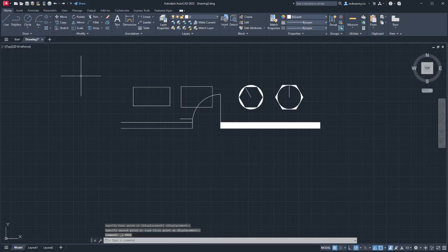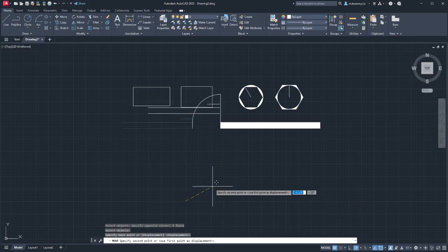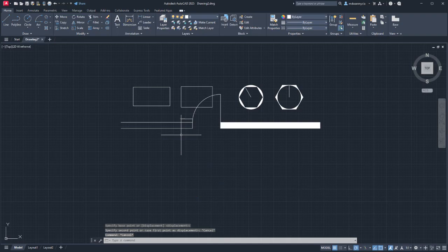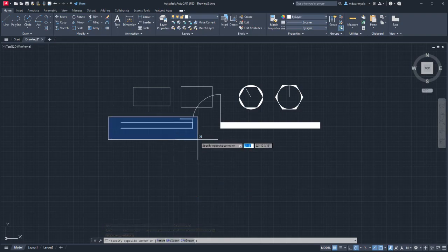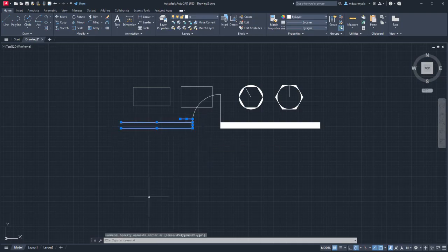Are there any alternative things? If you don't have anything selected, you can select the objects after starting the tool, hit enter or spacebar, and then you can specify whatever your movement might be. So you don't have to select stuff. That being said, for all of these tools where you have to select something, like the move tool, I always recommend you do your selection first.